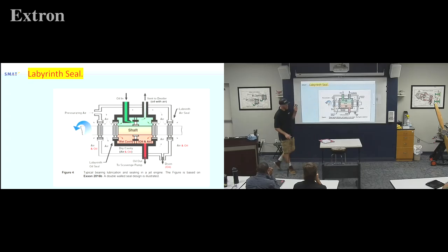They're just very, very close to each other. So we're pushing air in, and we're going to be pushing air through those tiny gaps. That's going to go with and head out. And on some of them, they even allow some air out the top because, well, why send it all through our oil separator if we know it's just air coming in? But the air will also come out the other side of our labyrinth seal.